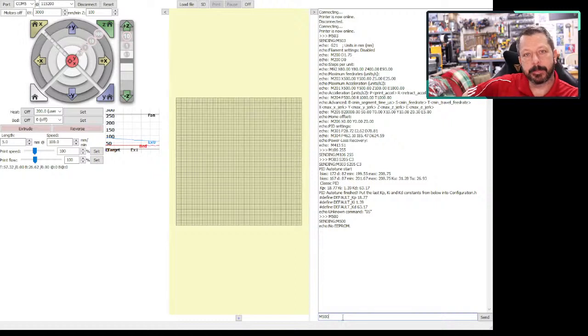of getting, in its current state with the material that I most want to use, to a set point temperature and staying there, not really overshooting too much, not really undershooting too much. If you've done any of your temperature towers, you know that it could be 5 or 10 degrees on some materials. Really makes a difference on layer adhesion, print quality, all these things. And so if I'm constantly overshooting and undershooting, I've got these varying layer by layer material properties that probably I don't want. There's a few instances where you want that, but generally you don't want that.